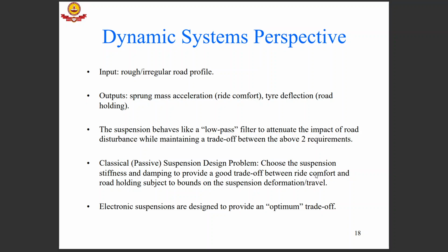Essentially, when we are sitting inside the vehicle, we will not feel the minor bumps caused by smaller gravel, but larger variations like speed bumps will pass through. Smaller gravels are there in large numbers, and they produce a signal which can be thought of as low amplitude and high frequency, whereas something like a speed bump will be low frequency because it's larger in size and comes less often.